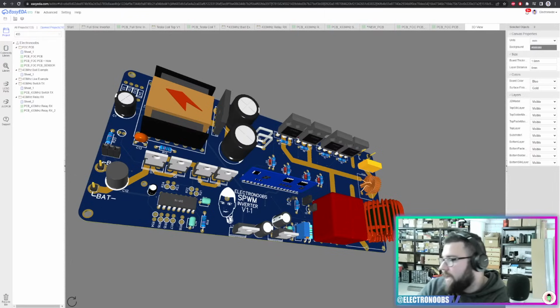We'll make a DIY SMPS video, maybe. I think I've made a power supply before with an Arduino, but I'm now planning to make one with an ESP32, which has a lot more power, a lot more frequency, much more speed. That's the problem with my previous power supply: I didn't have enough speed, so the voltage output feedback didn't have enough speed to control the PWM output for the MOSFETs, and the loop was getting slower and slower. But with an ESP32, I think I will have a lot more speed, so maybe we'll have a power supply with that as well.